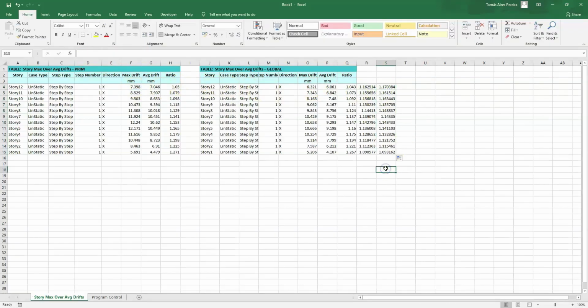We notice that, particularly on the upper floors, the contribution coefficients of the secondary elements are slightly higher than 15%. However, up to the 8th floor, we are safe as they are all below 15%. There is a small contribution in this X direction that peaks at around 3% over the limit, which brings the check into question. We will also look at the other direction.